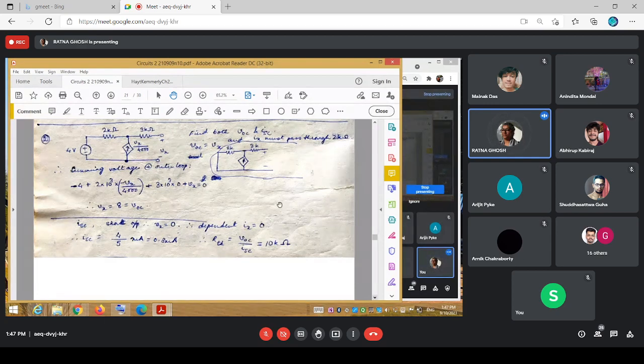So your equivalent circuit here depends on whether you want to draw the Thevenin or the Norton. The Thevenin would be five kilo ohms and this is 8 volts, and so this will be the Thevenin equivalent.